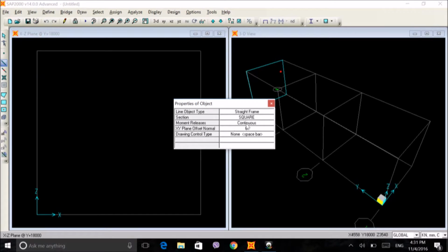but it's very important to come here. Unlike beam and frame, we cannot use continuous. If we make it continuous, then there is a moment coming out at the node, but in a truss, generally, if it is not a welded truss, it is a pin-jointed truss. This is pin.